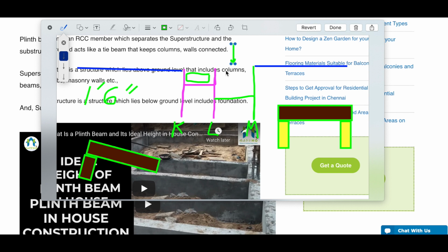Now I've got to work my way back into the building, because remember, when we see the video, approximately 2 to 3 floors have already started going down together at the roof line. Remember, at the roof, they only have 4 pieces of rebar in the columns. I showed you this in the previous videos. If you were to remove one of these, by it failing, by rattling, you're now trying to hold up the structure with 3 pieces of rebar, and the stress and strain.